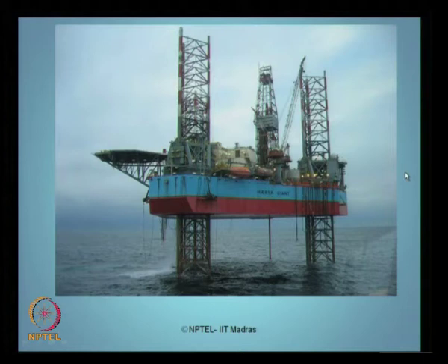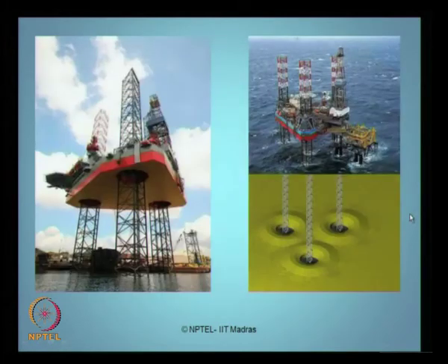Now the question comes, why are these structural members or these kinds of platforms called jack-up rigs? This is a closer view of this rig. You can see these 3 lattice towers, which we call the legs of the jack-ups, are installed. So these legs are protruded into the sea bed for better stability, and then the deck is jacked up above the sea water level to have enough freeboard for operation.